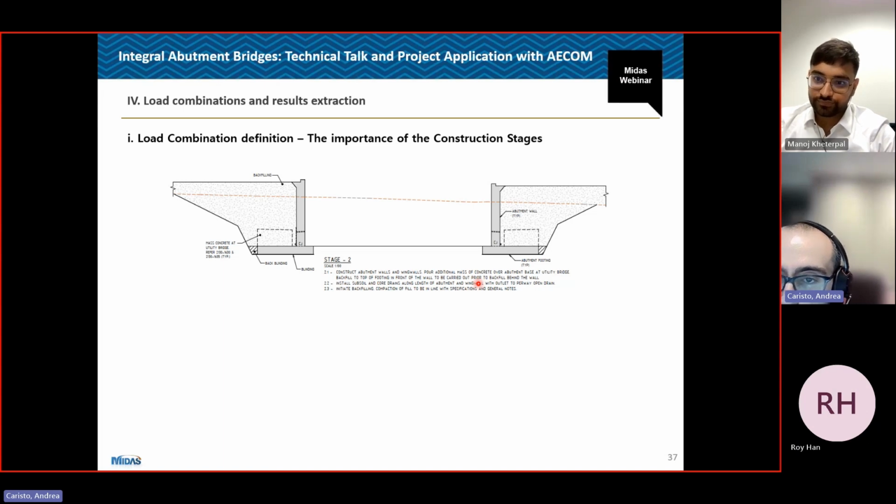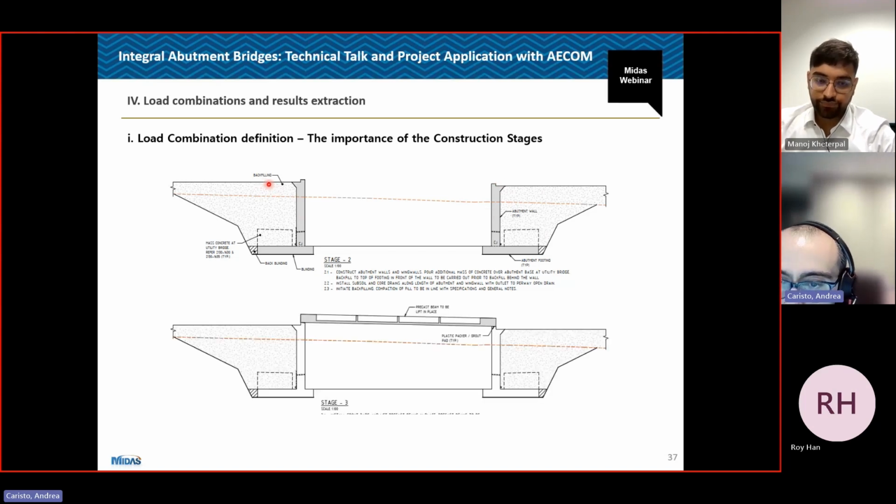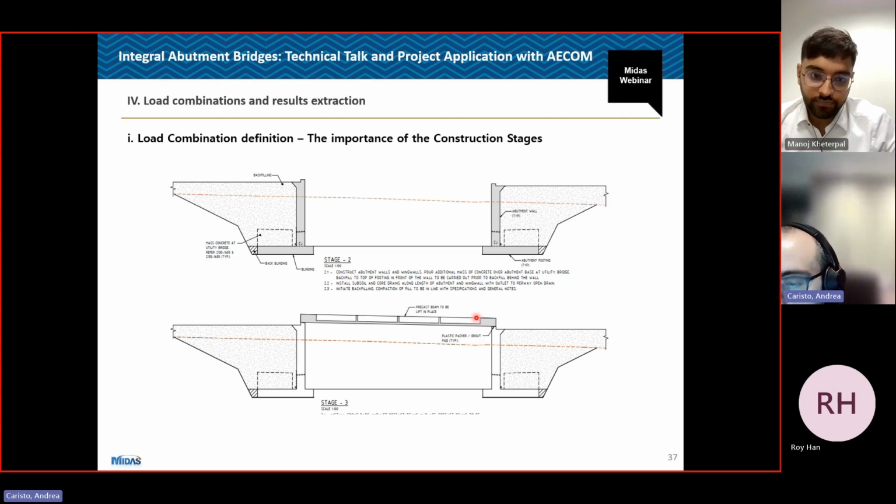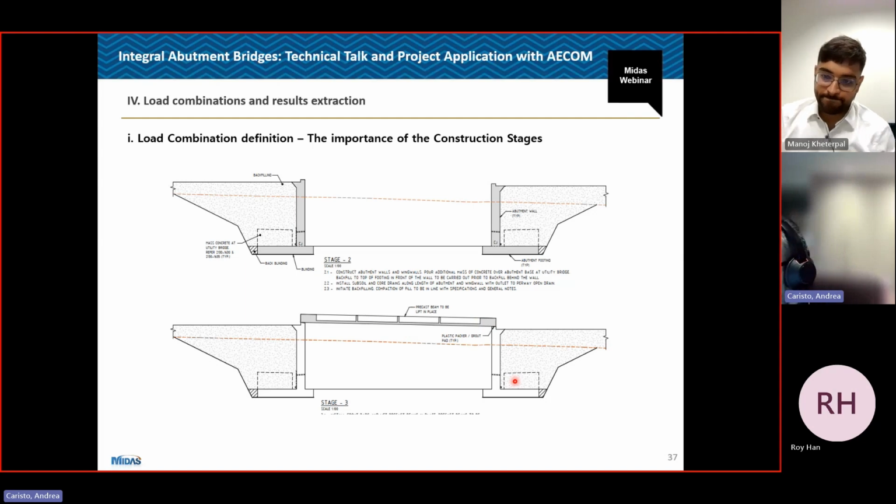For the bottom-up bridges, we looked at it before very briefly, but what we have is the bottom part of the bridge, the substructure, is built. Then the walls are backfilled almost to the top. Okay, you can see it here. Then the deck is brought into place. This was driven by construction timelines. And effectively, the contractor wanted to have complete disjointed erection of the deck from the erection of the substructure. So this is what we gave them because that's the need of the contractor.